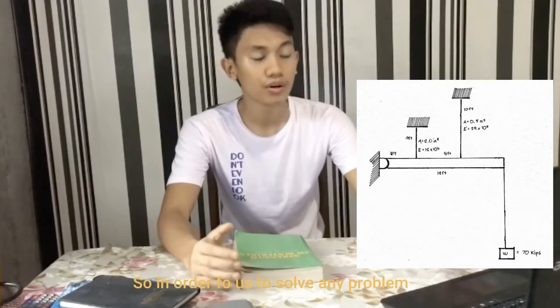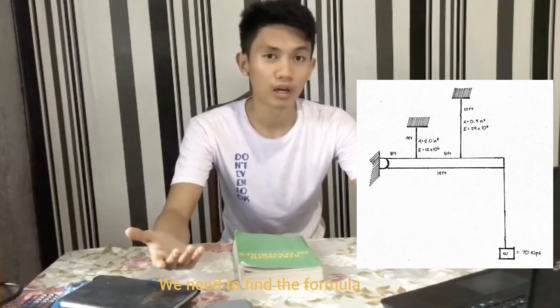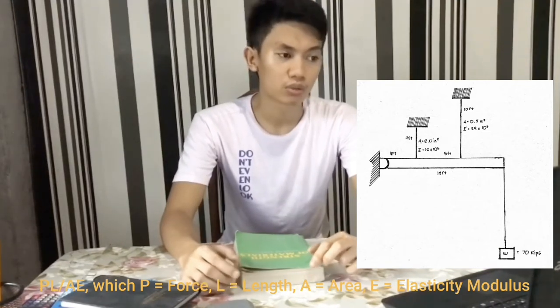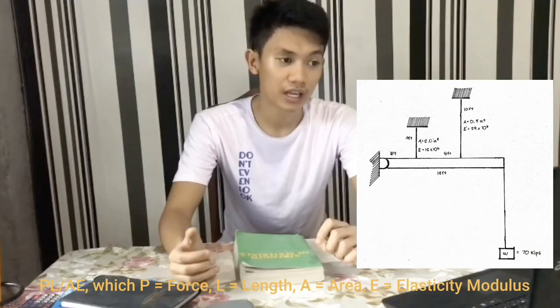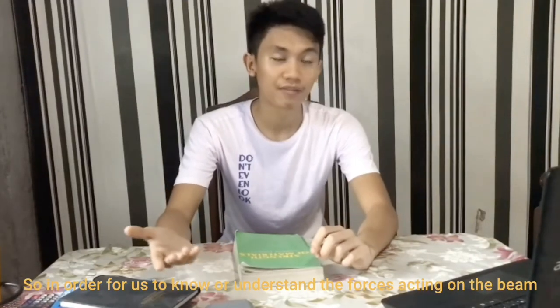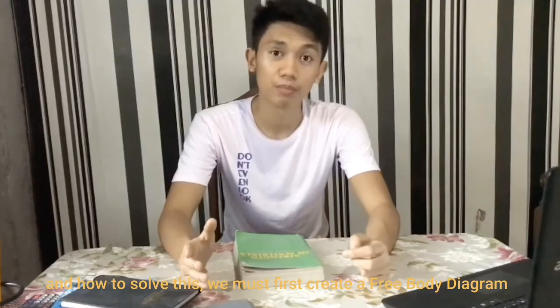In order for us to solve any problem, we need to find the formula. The formula for deformation is PL over AE, where P stands for force, L for length, A for area, and E for the elasticity modulus. In order for us to understand the forces acting on the beam and how to solve this, we must create a free body diagram.